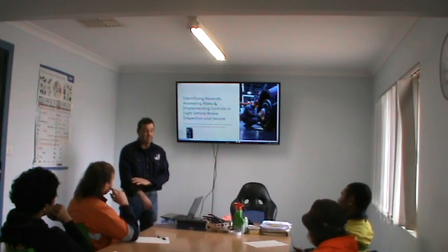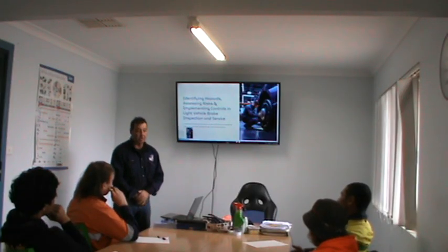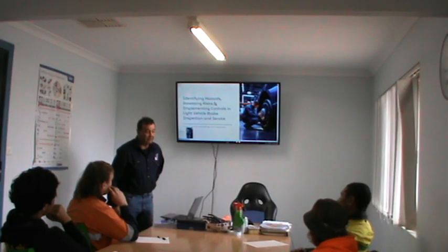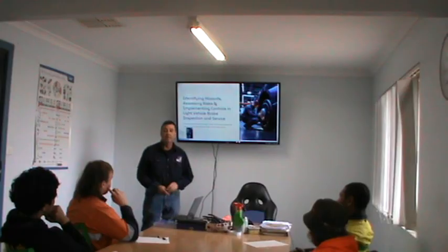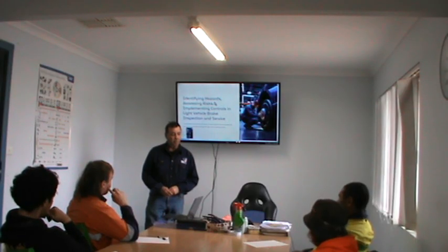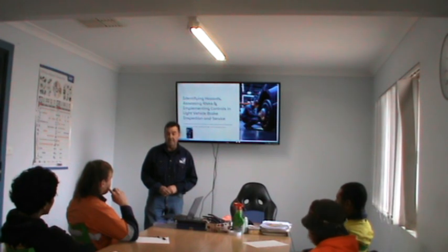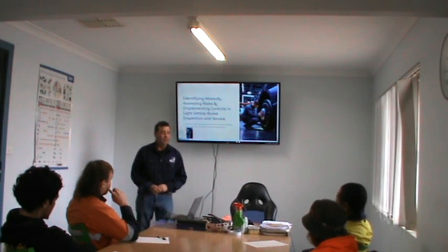We have brake dust. That's probably number one. Asbestos. Brake pads were entirely made out of asbestos back in the day. However, they have removed that content from it, but not all of it. And some companies might not have removed it at all. So we always assume that every time we're working on brakes, it's going to have asbestos in the brakes. So we always got to make sure we're aware of that and how we deal with that. We have to know how we're going to deal with that.